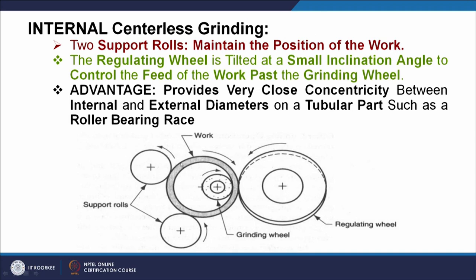There is one additional advantage: when internal centerless grinding is performed, it produces very good concentricity between the internal and external diameters. That is especially useful for roller bearing races.